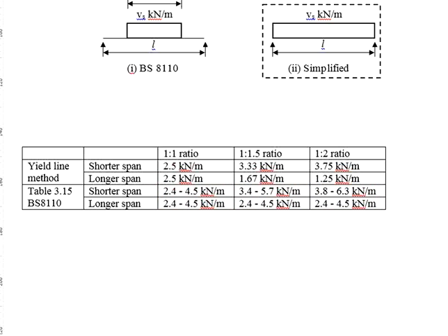In the case that you do not have the table with you where you need to do the design, the U-line method may be used, but you will expect that the loading will be slightly smaller than what you can anticipate from the British Standard. Therefore, you can conclude that the British Standard analysis is more conservative.